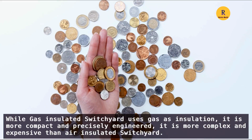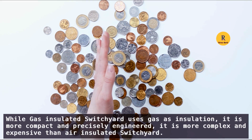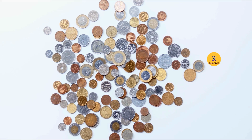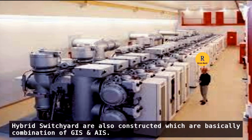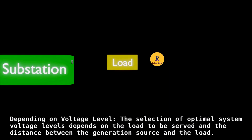A gas-insulated switchyard uses gas insulation; it is more compact and precisely engineered. It is more complex and expensive than an air-insulated switchyard. Hybrid switchyards are also constructed, which are basically a combination of gas-insulated and air-insulated substations.